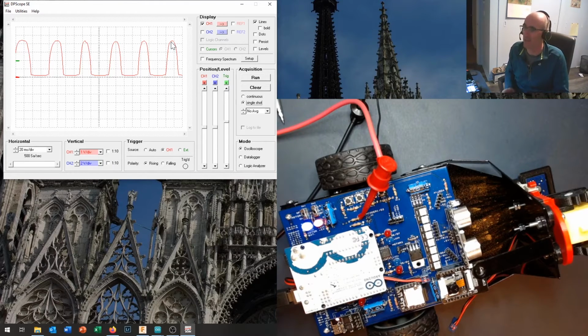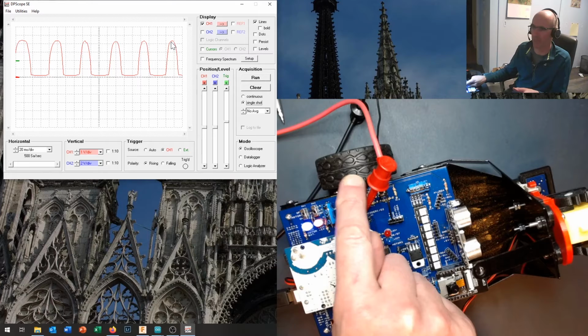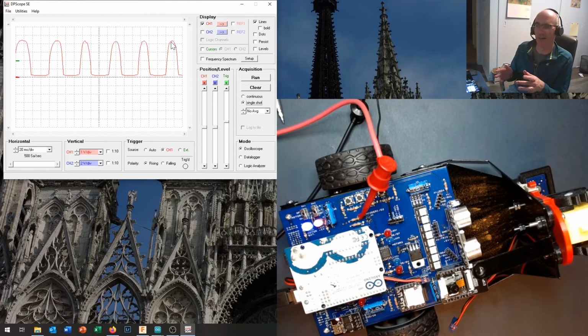And you can use that to determine the speed of your wheel. So right now I've talked about using the encoders for measuring distance, but inherent in measuring distance, since we can also measure time, well, distance divided by time gives you your velocity. So you can use these to measure and help control the velocity of your wheels as well. So all sorts of neat stuff going on right there.